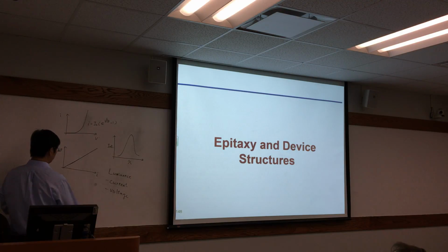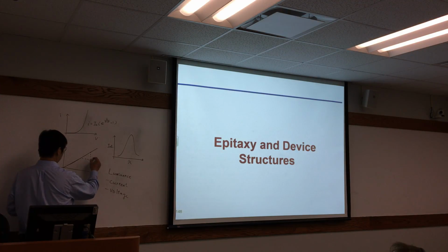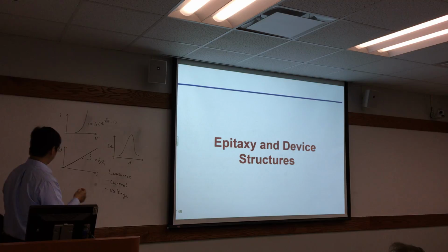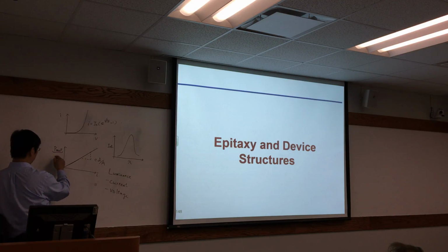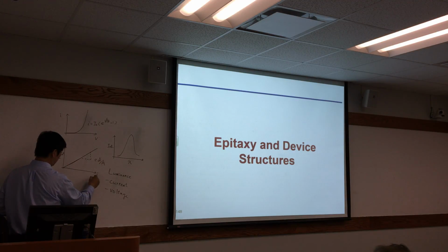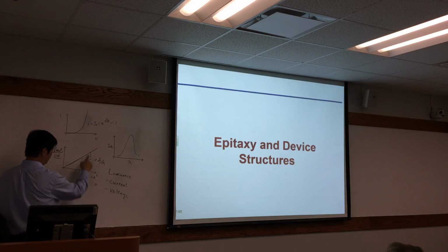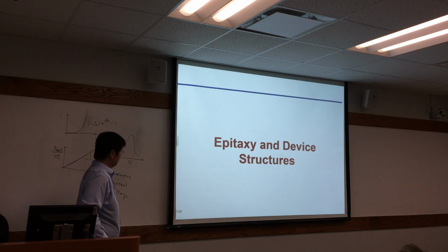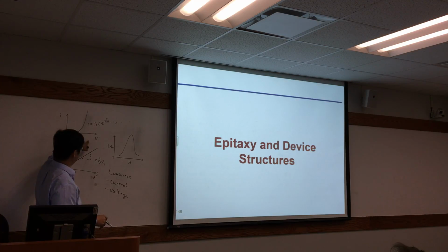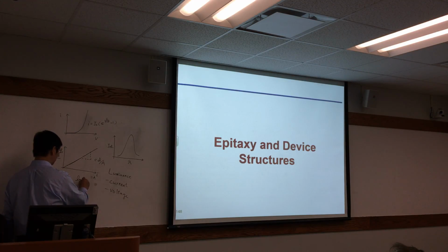And from the slope here, we can obtain the candela per amp. Because for the output here, you can use, for example, the candela, right? And here, you can use amps. So from the slope here, you can obtain the candela per amp. And also, because you have IV, you can have the lumen per watt as well. So here, if that is linear, that implies the I over the candela per amp is linear. Right? So how about lumen per watt?